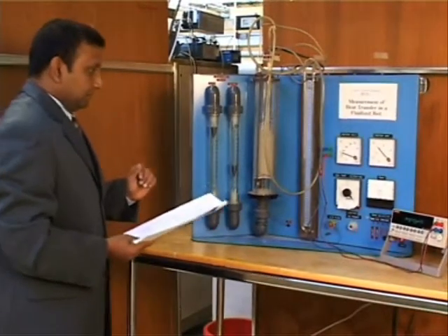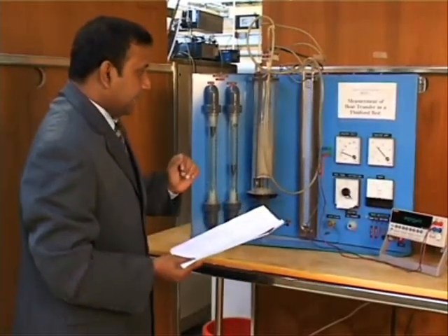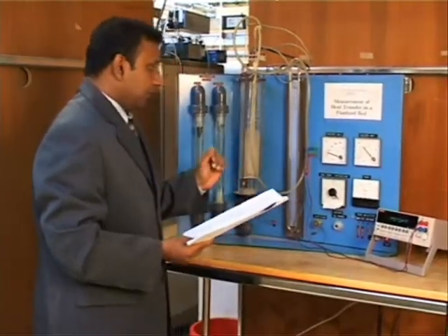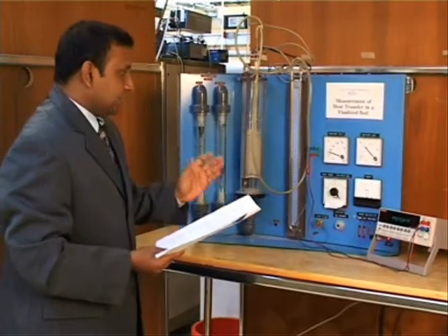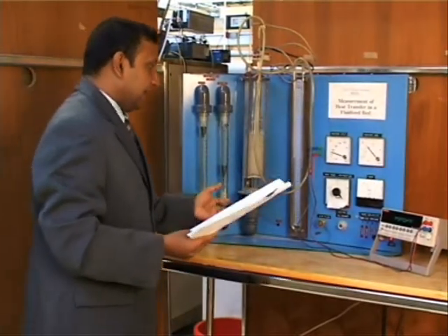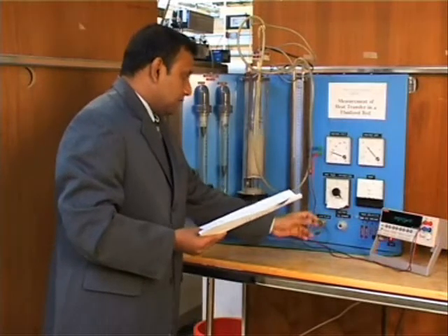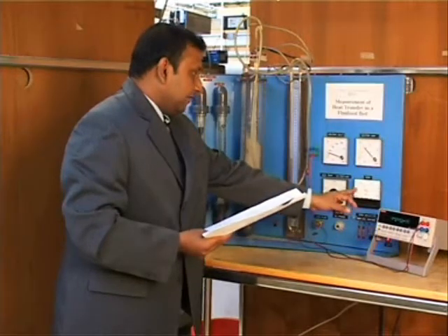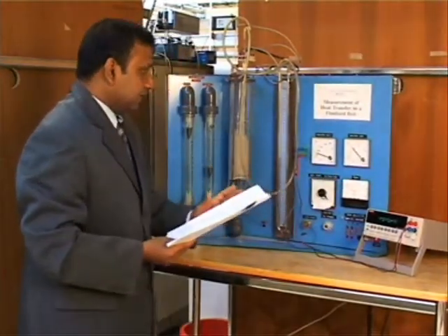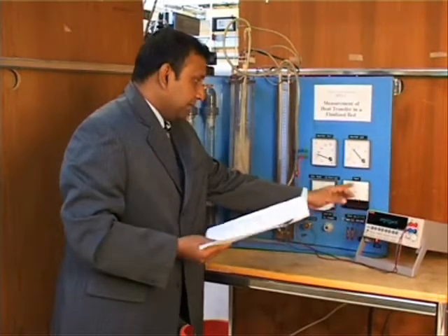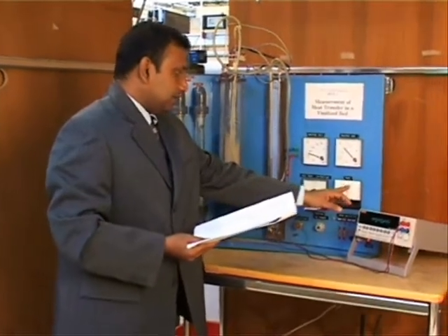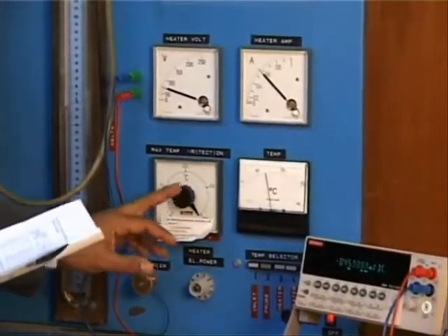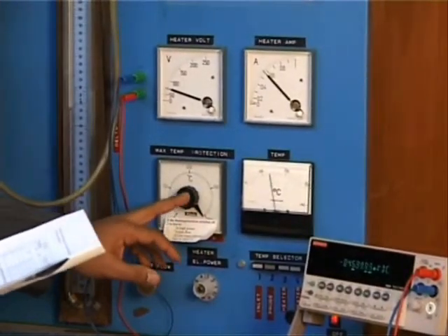But I would like to mention here, when you are taking these readings, this is very tricky, and you have to have very good patience to reach the equilibrium points. If you are in a hurry and adjusting this electrical setup too fast, you will never be able to get stable conditions. And even if you may read the same temperature, it is not controlled by the process itself. It can be controlled by the electrical protection guard.